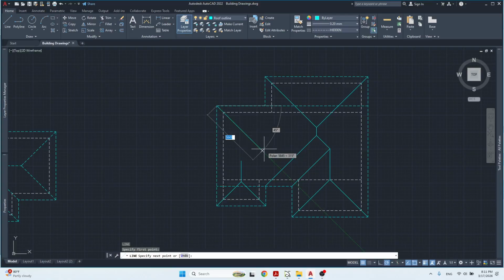We have the 45-degree line this way, or the other 45-degree line this way, right? So where these two hip lines meet, that's where the ridge is going to be. So we are going to put a ridge right here. And this ridge is going to be meeting up with this hip line running here, right? And if that happens, remember what we said, whenever this ridge meets up with this hip line, we're going to get rid of the rest of this hip line right here.